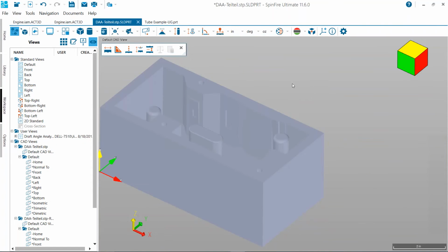Yeah, on thin-walled parts, if you do a section cut across that, you may get varied thickness where it shouldn't be because of that. That's probably the first thing I would try, is retessellate that. And if not, then send me an email and let me know.